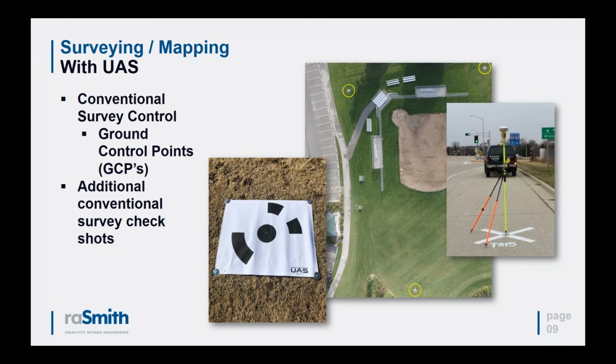And then ultimately, how we prefer to do it anyway, is you have to collect survey grade measurements on these points as well. We usually use survey grade GPS, using a Wisconsin DOT prescribed method for obtaining these, where we set up a GPS unit, as you see in that picture on the right, on the point, and then we pull it off.